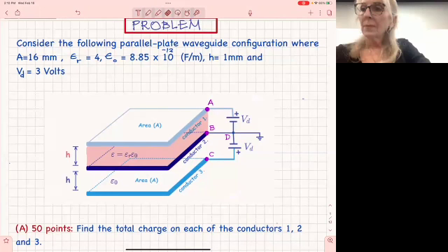First of all, the capacitors are tiny. They need very small thickness, and they need no losses. So what they do, they put a silicon oxide here. And the silicon oxide can be from a micron to less, or a fraction of a micron. And then they put a metal here. And then of course they have another metal here because they want the field to be confined. And that's an MOS capacitor. Very popular. All of the things that we're using about the MOS capacitors is exactly what we know here.